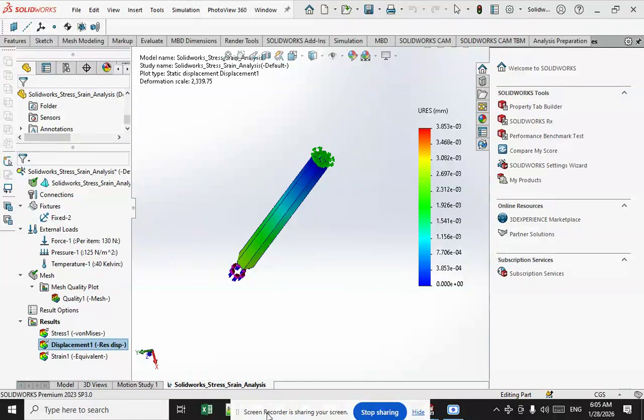These values reflect the degree of confidence the responsible authorities have in their understanding of the load environment, their certainty of the material strength, and the accuracy of the analytical techniques used in analysis, the value of structures, the value of the lives of those flying, those near the test fixtures, and those within the building. The factor of safety is used to calculate the maximum allowable stresses. The formula is: maximum allowable stress is equal to ultimate tensile stress divided by factor of safety.